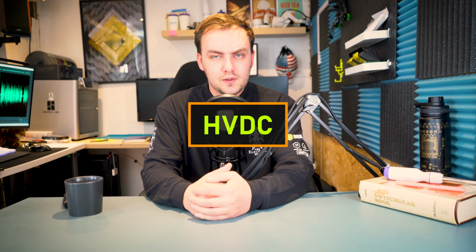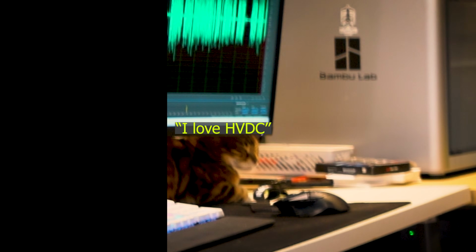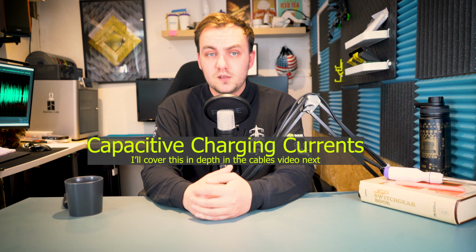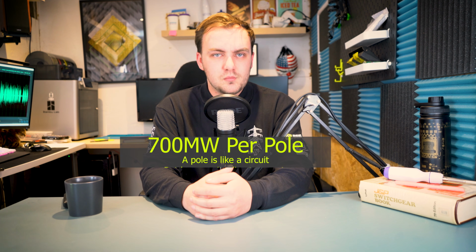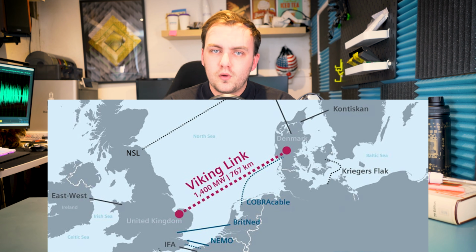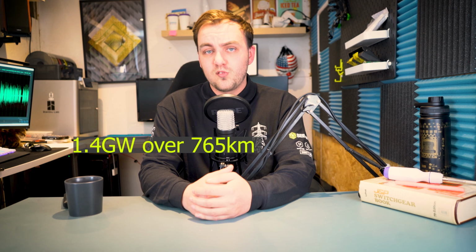High voltage direct current, or HVDC, is another cable technology that's all the rage right now. It bypasses some of the limitations of AC cable systems, like capacitive charging currents, that restrict cable length, and is more efficient for long distances. A HVDC cable can carry around 700 megawatts per pole, and systems like Viking Link, which connect the UK to Denmark, can transmit up to 1.4 gigawatts over an incredible 765 kilometres or 475 miles.